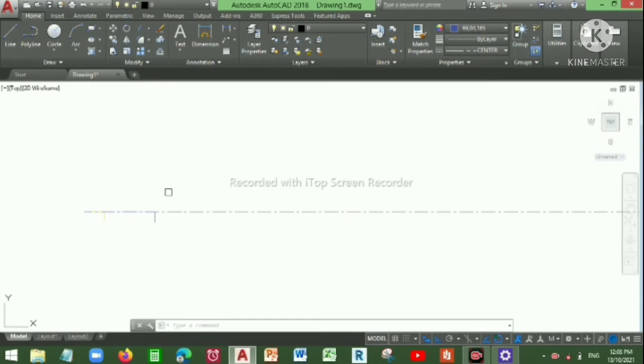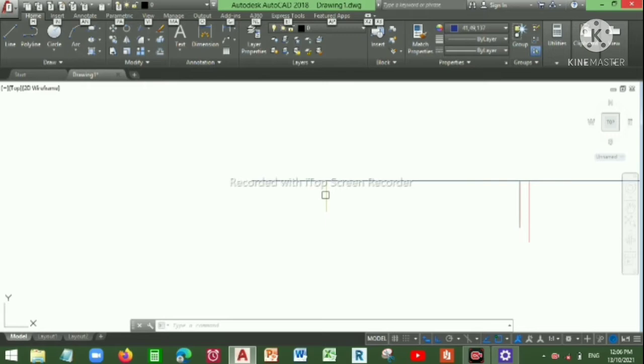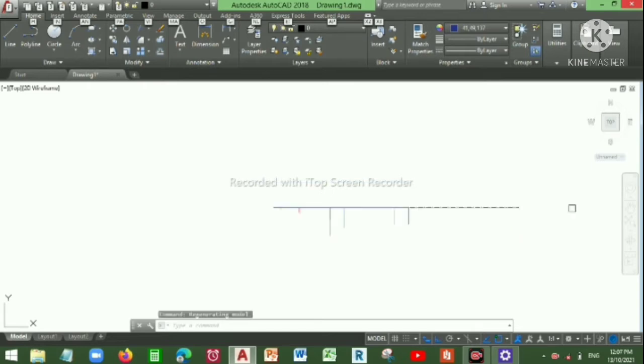So as you can see, I have marked all my points on the chainage on the chain line. This is 0 meter, the initial point. Next is 0.870, 3.114, 3.220, and so on till the end at 30 meter. I highly recommend you do the same, because doing so will help you to draw your perpendicular and other offsets easily.